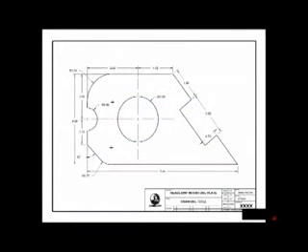Layouts are the most powerful way of creating plots in AutoCAD. Their benefits even go beyond the viewports, plot preview, and naming features that we've seen here. If we can incorporate layouts into our workflow, we've taken the first step towards using even more powerful features like sheet sets, page setups, and publishing.